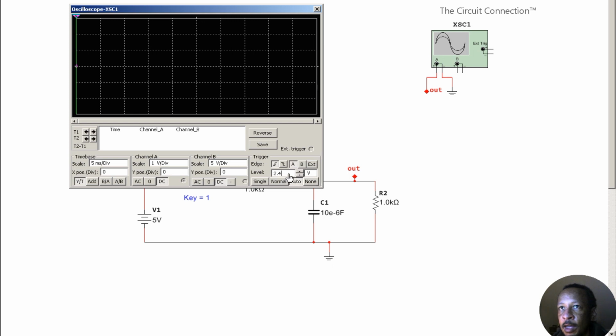So I took that away, and make sure that the level that you trigger at is going to be a little bit more than 0 volts. I'm going to put it in millivolts, and I'm going to use something suitably small, like maybe 1 millivolt. I wouldn't go any lower than that. Maybe make it 5 millivolts, so that when it rises above 5 millivolts, that'll trigger the oscilloscope to take a snapshot of what's going on until the end of the screen.